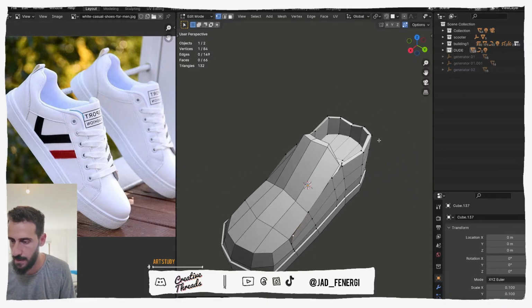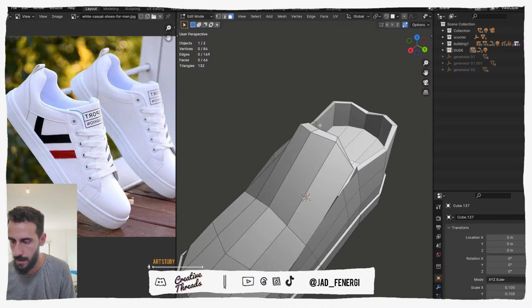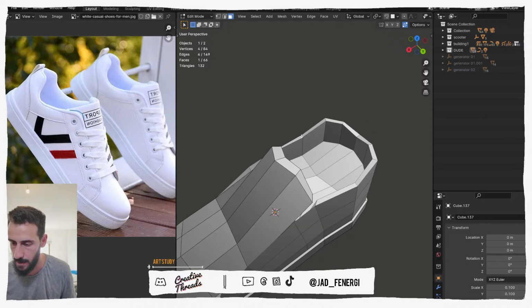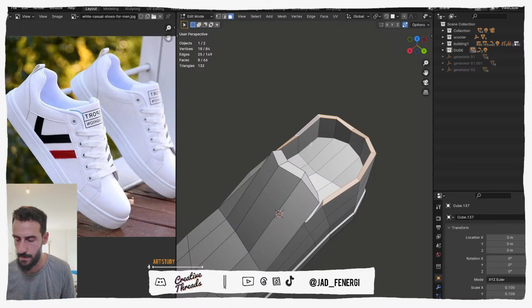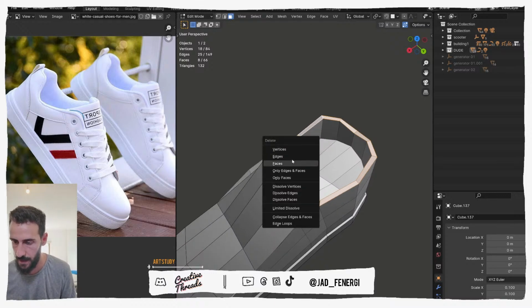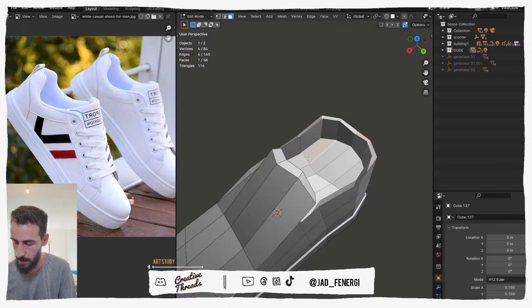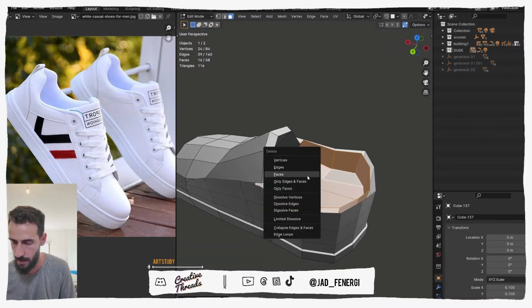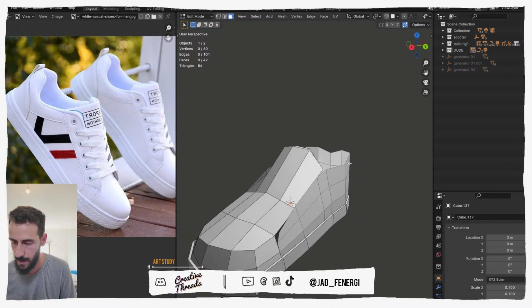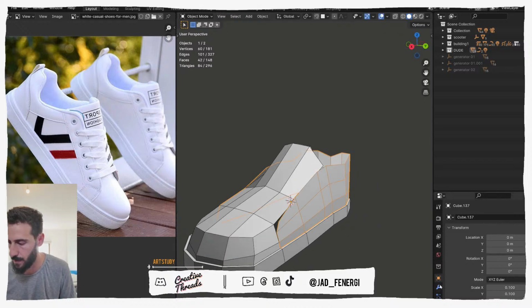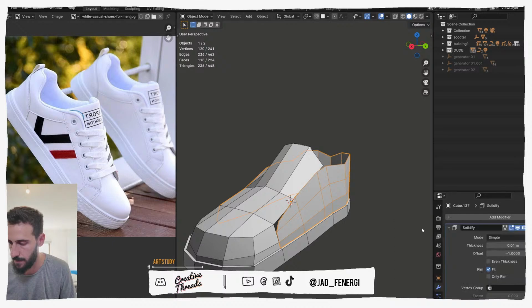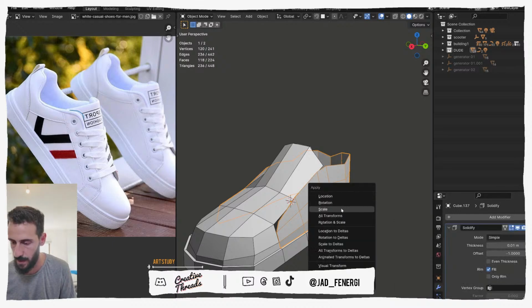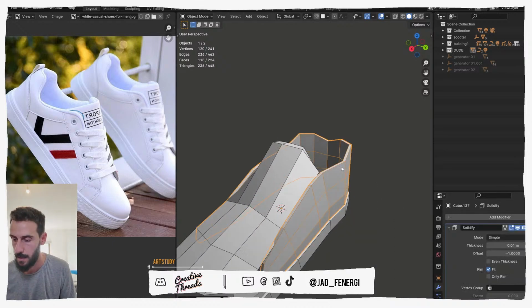And you know what? Instead of adding the thickness ourselves, I'm gonna delete these faces and I'm gonna delete the inner faces by pressing L. So everything linked is gonna be selected. I'm gonna delete those faces. And now what we can do is just add a solidify modifier, press Ctrl A, apply the scale to make sure that it works properly. Add just a little bit of thickness.